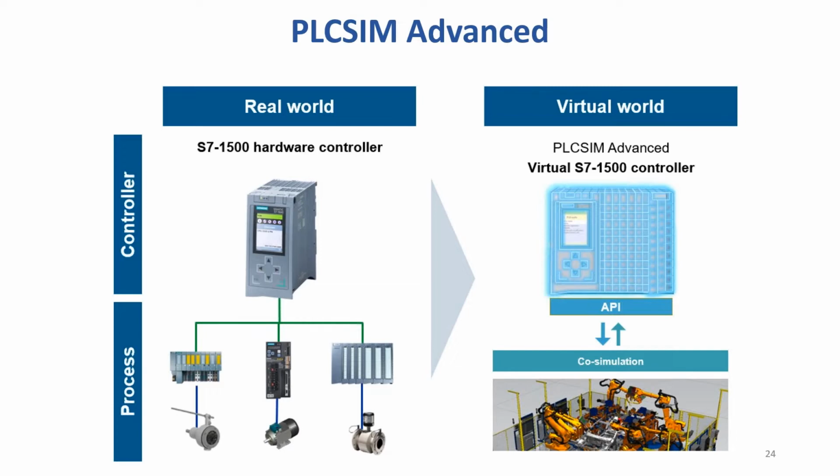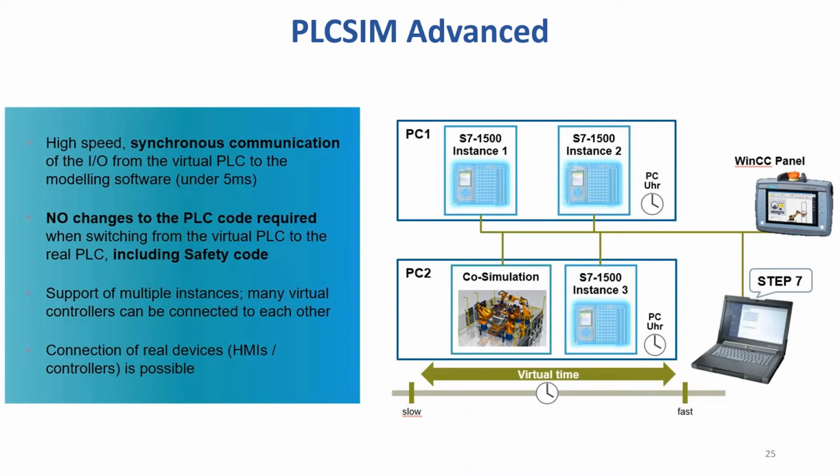PLCSIM Advanced is a great software in the loop tool that provides a virtual digital twin of an S7-1500 controller. And here's another nice diagram of how PLCSIM Advanced interacts with the WinCC panel, which is the control panel for equipment. And you can do Step 7 programming, upload and download between the PLCs.